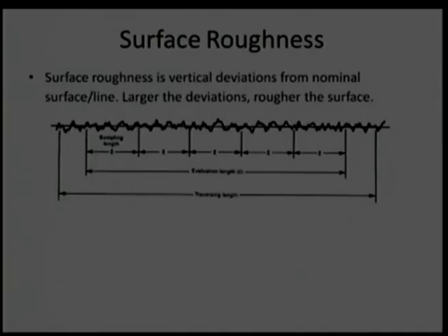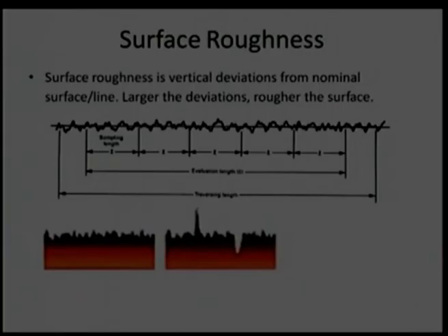We know the surface roughness is statistical. We cannot find a single value. So in that case, we try to average these 5 sample lengths, and whatever data comes, that will be the mean surface roughness. So there will be some mean value of surface roughness as well as a standard deviation. Having a larger number of sampling lengths will give a better result, but it will consume more time. That is why, as per the standards, they have come to the final figure of 5 sampling lengths, which gives reasonably good results. That is why we are choosing this mode.